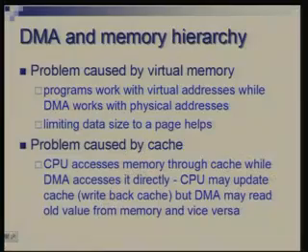What about cache? When you have cache, what problems can it possibly bring in? There is essentially a problem of consistency, because the CPU is directly talking to the cache and not to the memory, whereas a DMA device will typically have no access to the cache. It can write to the main memory or read from main memory. So, there is a problem of consistency.